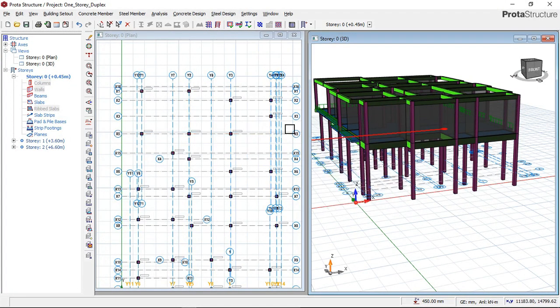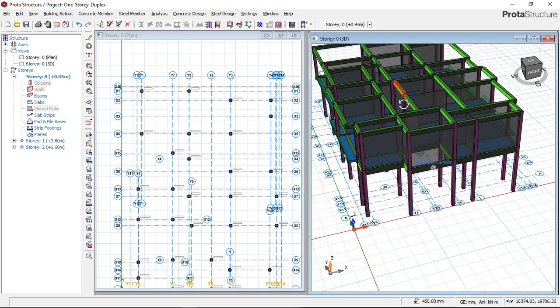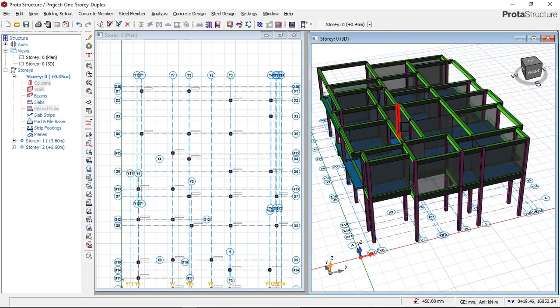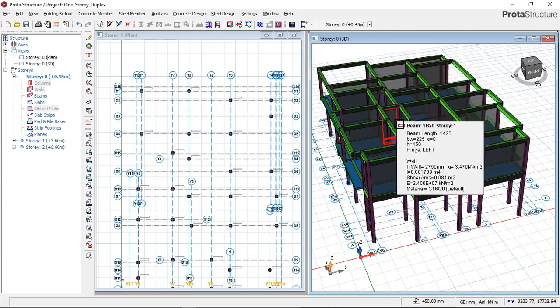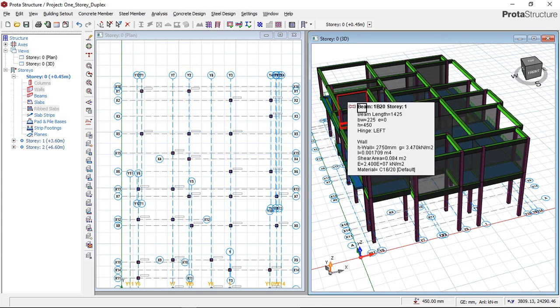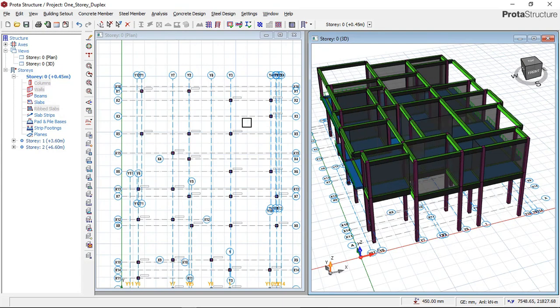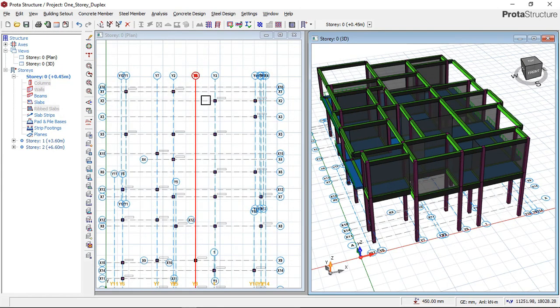In this case, because this is a live project, the soil bearing capacity that was given to me as a structural engineer for my client, Engineer Tega, was 125 kilonewton per meter square. So that is the bearing capacity factor that was given to me. So right now, I'll just click on this place.